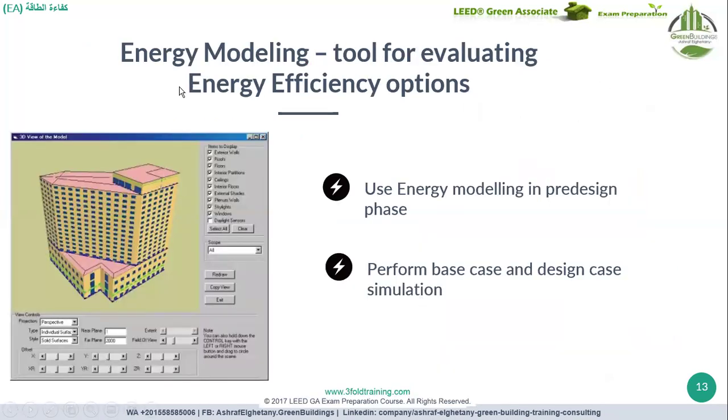We spoke about the energy model and how the energy model takes input about the building's physical materials and building physics, or we can say the roofs and every part. We put, for example, the R value or U value for these materials and start to estimate the energy consumption. Of course, the tighter and better insulated the envelope, the less the energy.